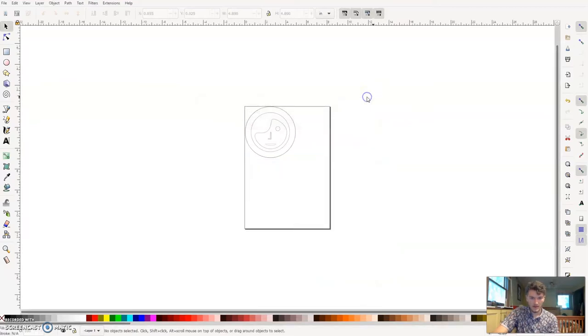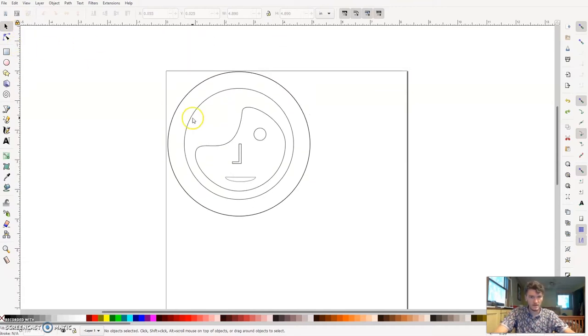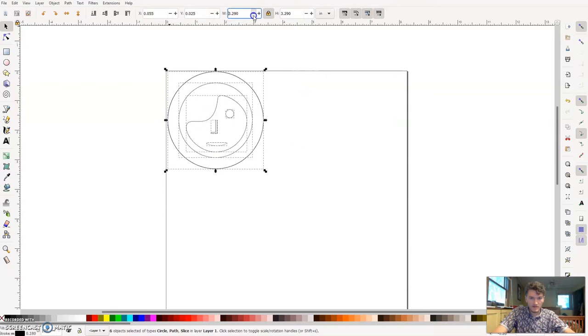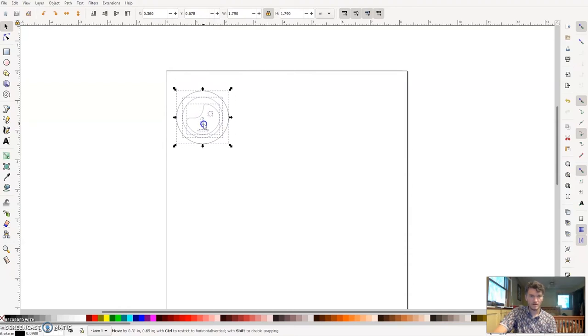And then once we have that, something like 5 inches, and I think 5 inches is a little big. So I'm going to go ahead, select this, and just lock the width and the height, and bring it down till we like it. I think 2 inches is nice. So now we have a roughly 2-inch section, and we know the size of this. So when we print it off and export it to the laser, it should be about 2 inches in diameter.